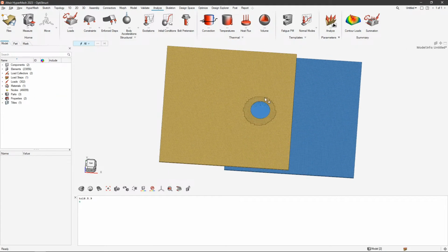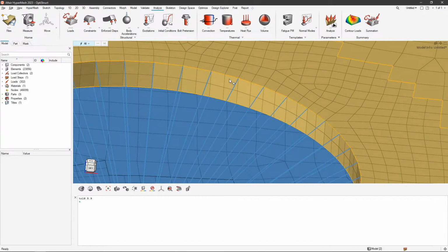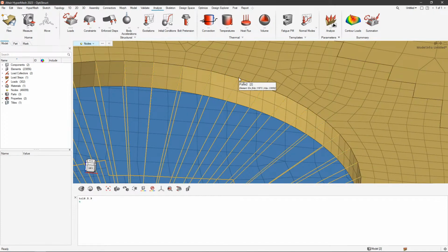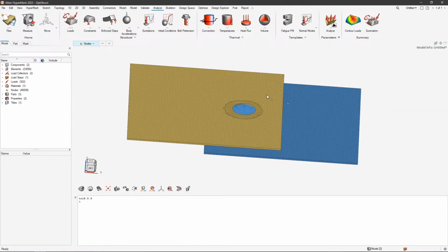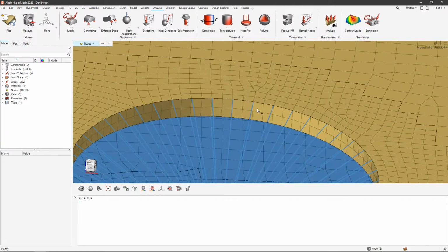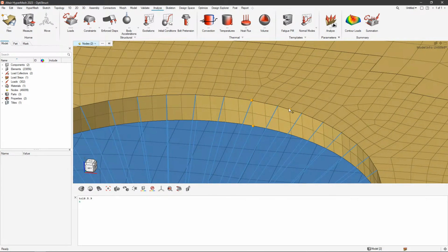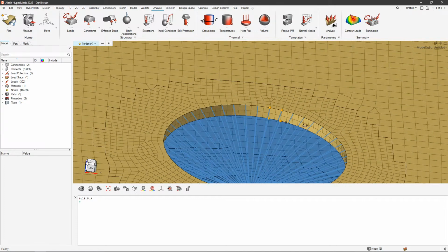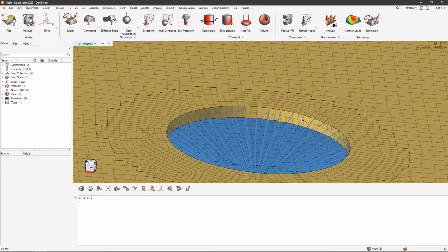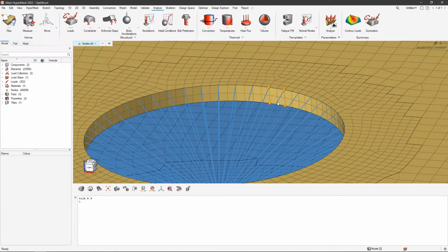So the broken FEM model has a refinement here. And the problem was we were dealing with subgraphs. Subgraphs meaning we had built a graph for a complete model. And then we did a subgraph where only the slave nodes of the RBE were taken into account. And then we looked for connected subgroups. And that resulted here in 180 different subgroups, which is not the expected behavior.